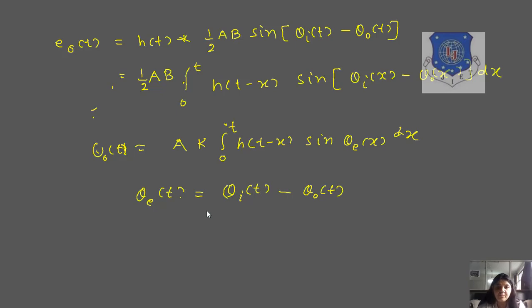A different loop filter enables the PLL to capture and track the input signal with different types of frequency variation. The loop gain also affects the range of trackable frequency variation. Such a PLL can be helpful for the detection of phase and frequency.